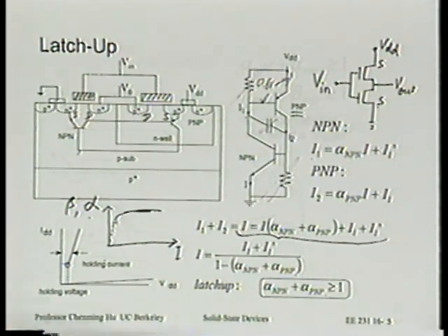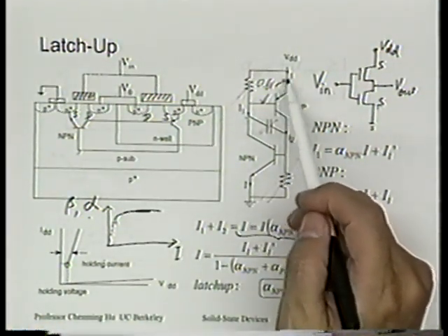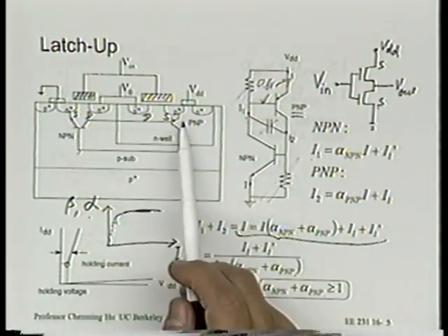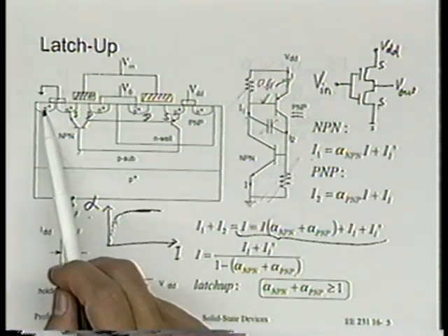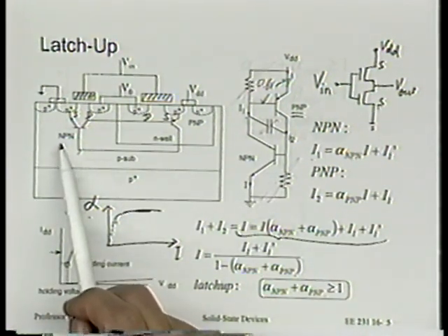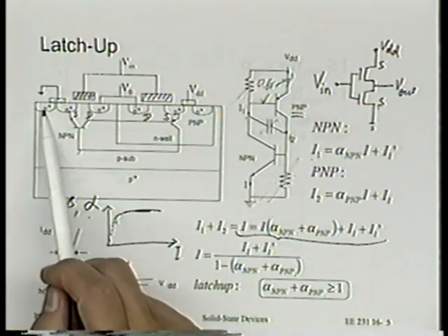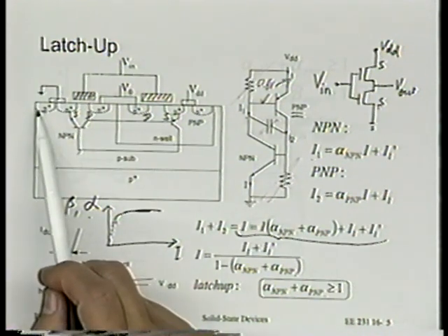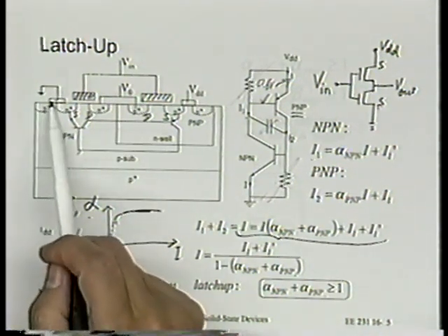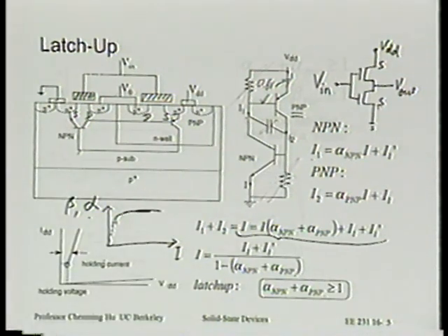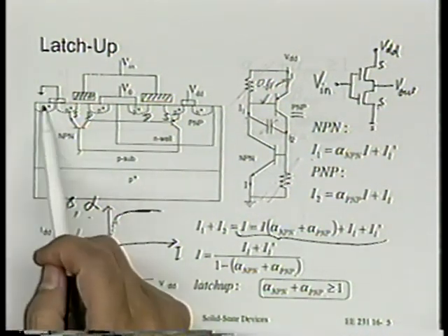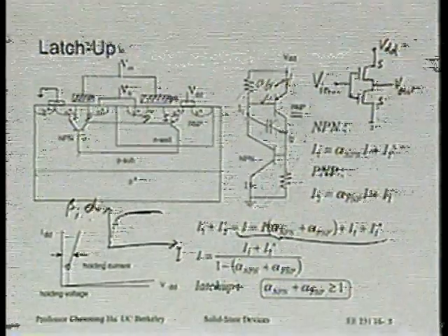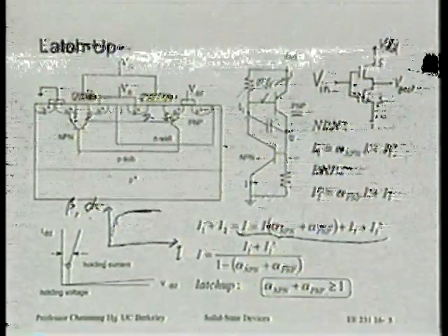All right? Okay. So how can we prevent this junction from becoming forward biased? Well, you simply short it. That's exactly what we're doing here, by trying to put a very good ohmic contact to the body, right? So that this base, the body, is the base, is that right? The substrate is the base. Yes? And then we try to short this contact to the source. That's the body, that's the emitter. So we're trying to short these two leads. Okay? But it turns out that doesn't work.